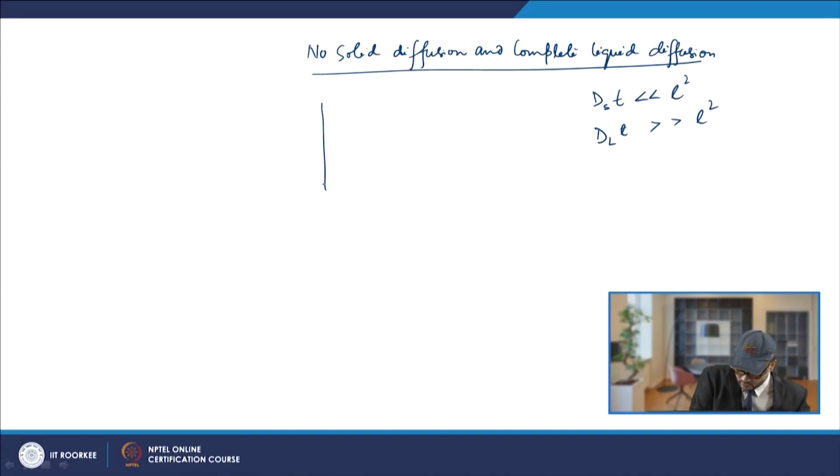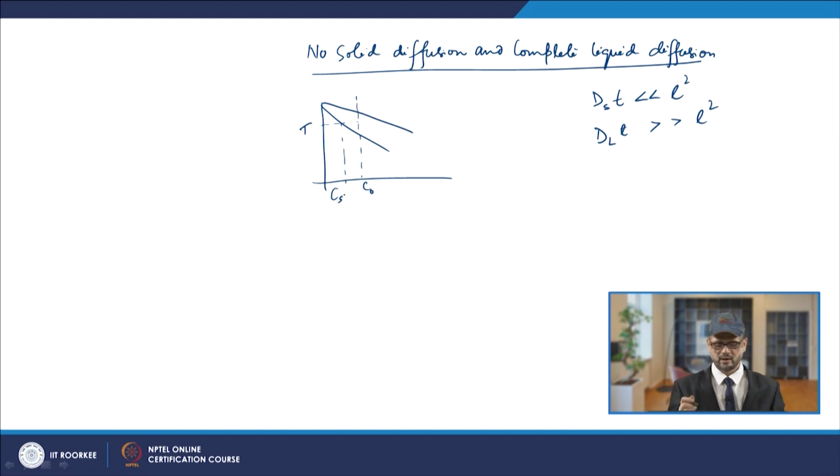So, at the end of the solidification, if you look at the solid phase, you do not have the uniform composition of solute. If you look at this case, we are coming to this concentration as C naught, and this is the temperature T. So, you will have this as the line CS, and this will be nothing but K C naught, and when it is drawn horizontally and touches the liquidus line, it will be C naught by K.